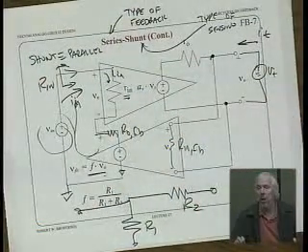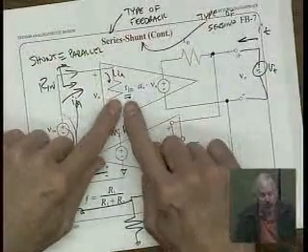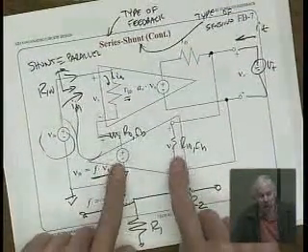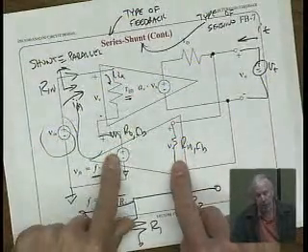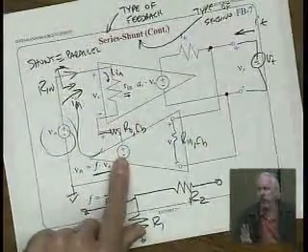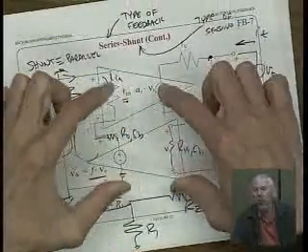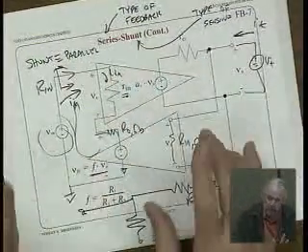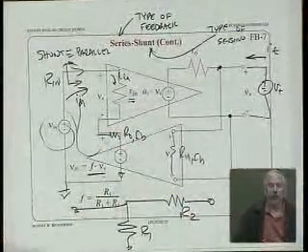So here's the way we're going to do these problems. I'm including the basic amplifier with its non-idealities: finite input resistance, finite output resistance. I'm right now not including the finite input resistance and finite output resistance of the feedback network. After I go through all 4 cases, I will then put in the R in and R out of the feedback network and get a new set of equations. And that's when we'll take care of the stuff that you're worried about. That may not be obvious, but there's always a resistance there because it's coming from this feedback network, right? So that's how it shows up.